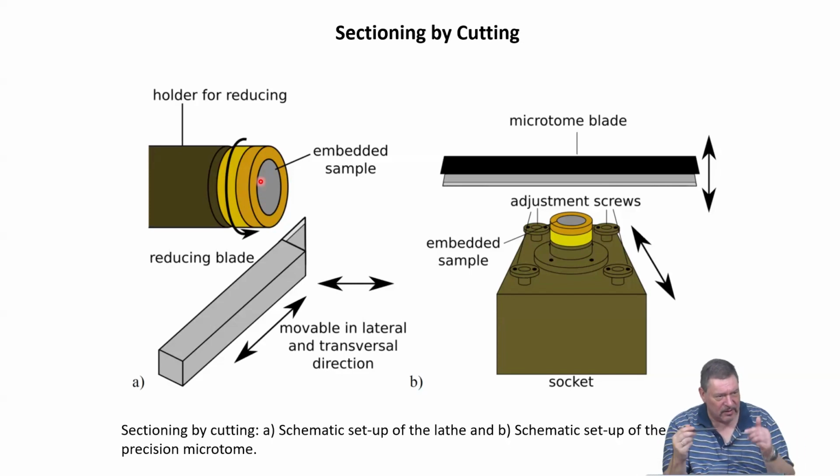and come from the backside or from the side of the sample entering your volume. If you have done this dimensional reduction, then you can use a microtome with a sharp blade, preferably a new diamond blade, and then basically cut, right, by slicing over the top of the sample.